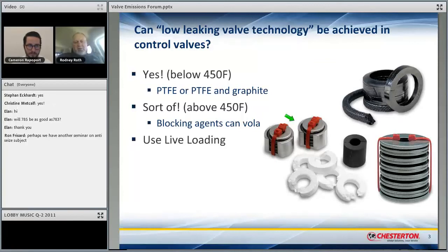And so those are bell washers. Those are engineered for us. The stack height, the OD, the ID, everything's done off of measurements that are taken in the field, and the loading and the way they're set up, whether they're in series or parallel or a combination, are all part of the loading required for the specific application that our team's designing it for.